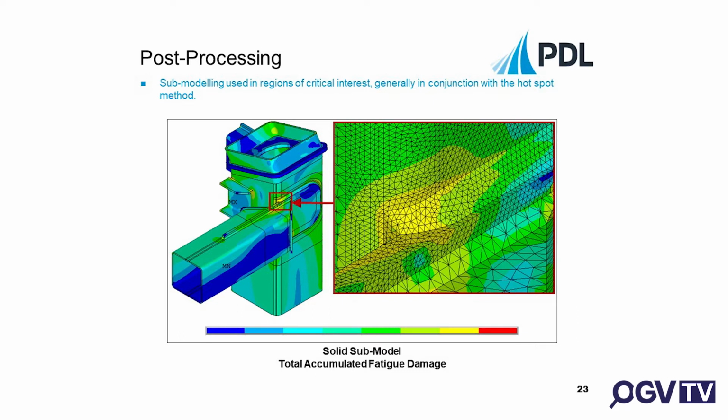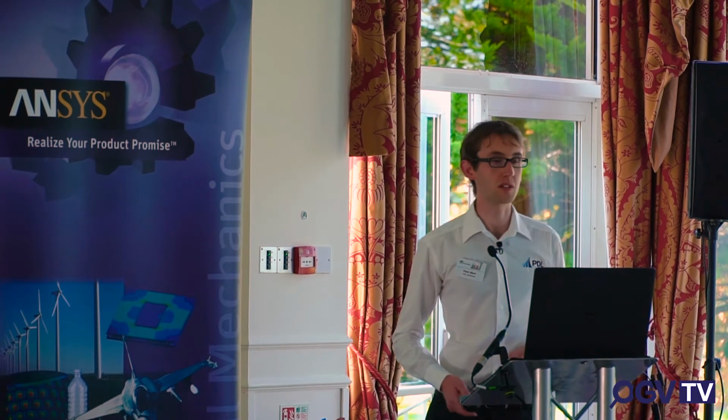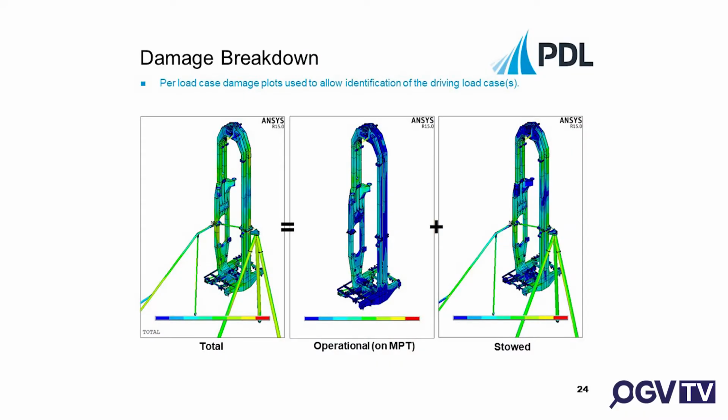So yeah, it's just showing you can go to quite a lot of detail. In this case, it was a fillet weld, and then we had probably the gap between the plate, and you could go in and look at the toe, but you could look at the root as well, and do all that very in-depth analysis for a particular critical detail.